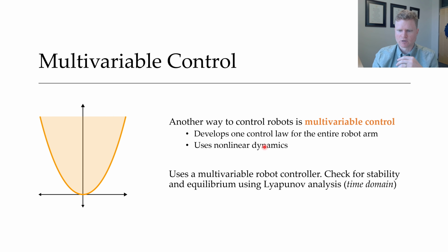And that led us to something called Lyapunov stability analysis. Now, I'd point out that all of our analysis here was performed in the time domain. The basic idea for this analysis was, we thought about the energy contained in our system, and we wanted to show that when we apply our controller, the amount of energy in the system decreases over time until I come to rest at an equilibrium position.